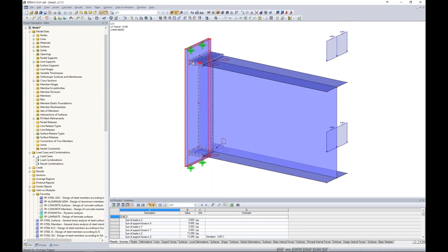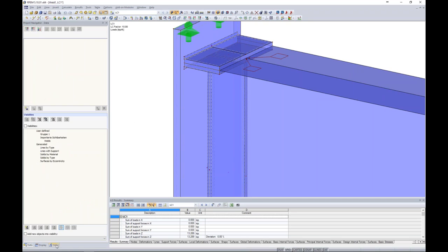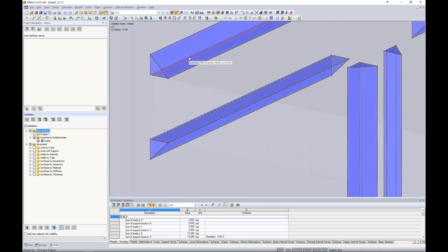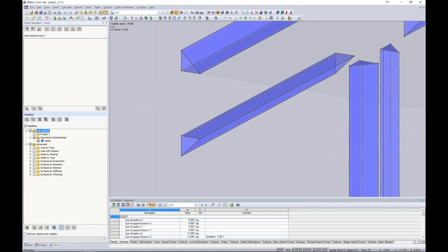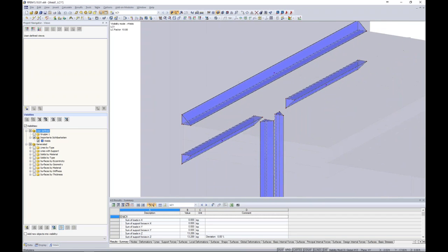So you'll notice we have many different lines and elements framing into the front side of the surface A, but we don't have it shown on the back side. So how about the welds? Well, I created a user-defined view here, and I can turn this on, of my weld solid. So zooming in here, you can actually see the triangular shape of this fillet weld, for example. Now, this weld is just another solid element.